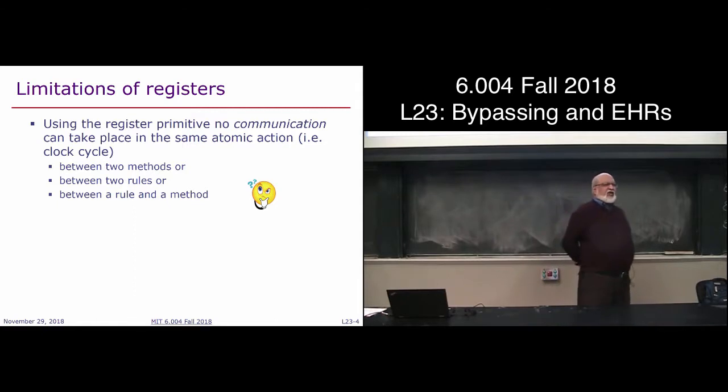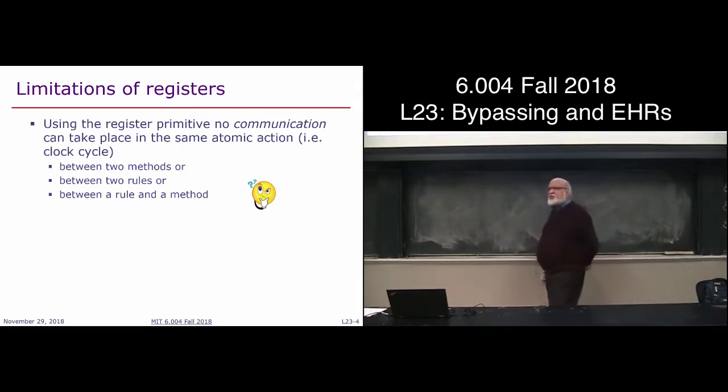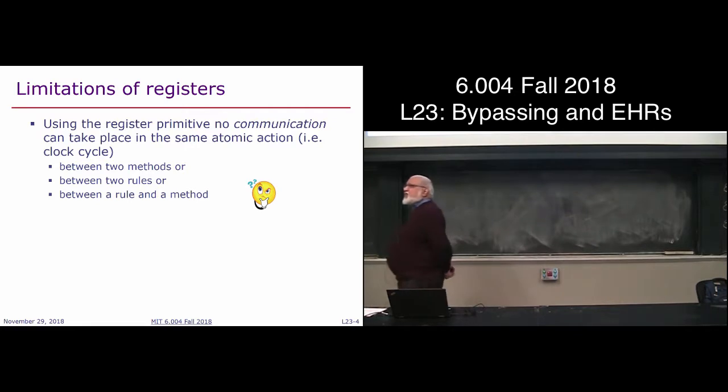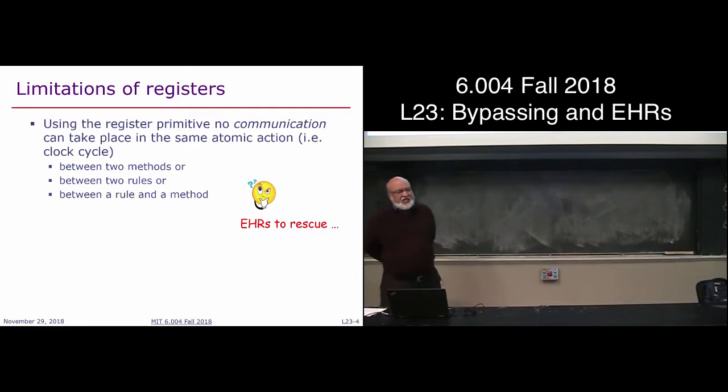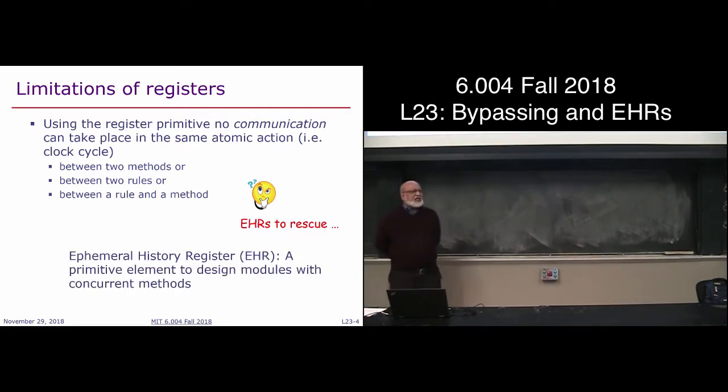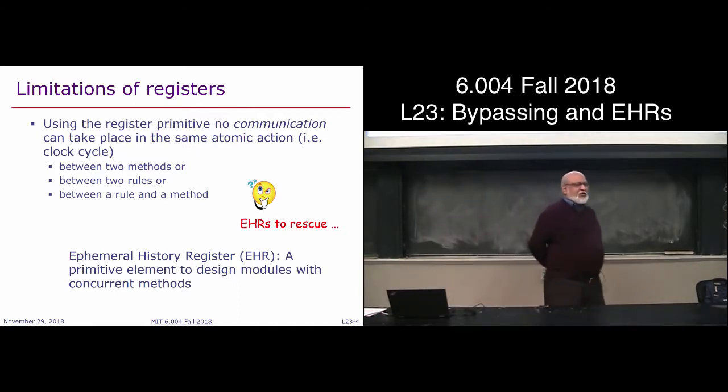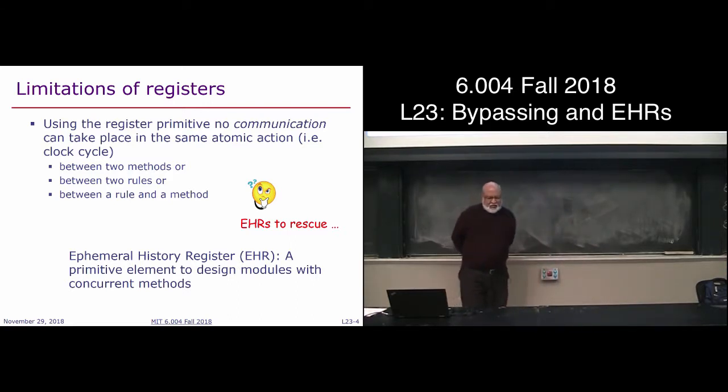And actually there are quite a few solutions, and I'm not going to give you the history of them. It depends in the eye of the beholder, but some of them are pretty ugly. They will turn Bluespec from a high level language into a very low level language. So this is the solution that I like best, which is called EHRs. EHR stands for Ephemeral History Register. A mouthful of a name, and I won't go into why we named it like that, but EHR is a primitive element to design modules with concurrent methods.